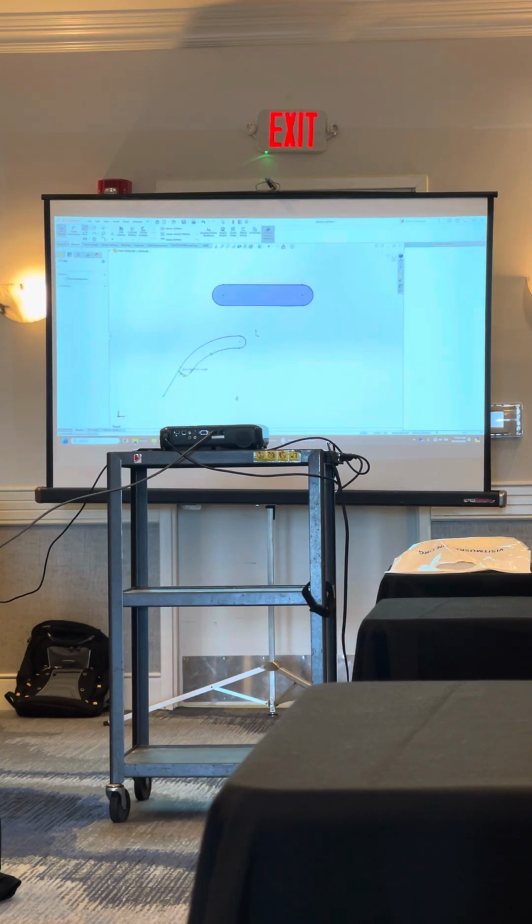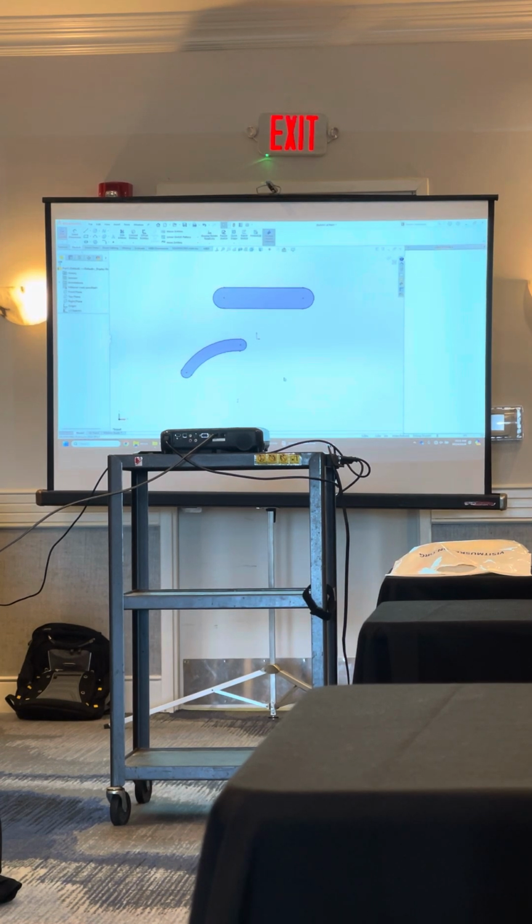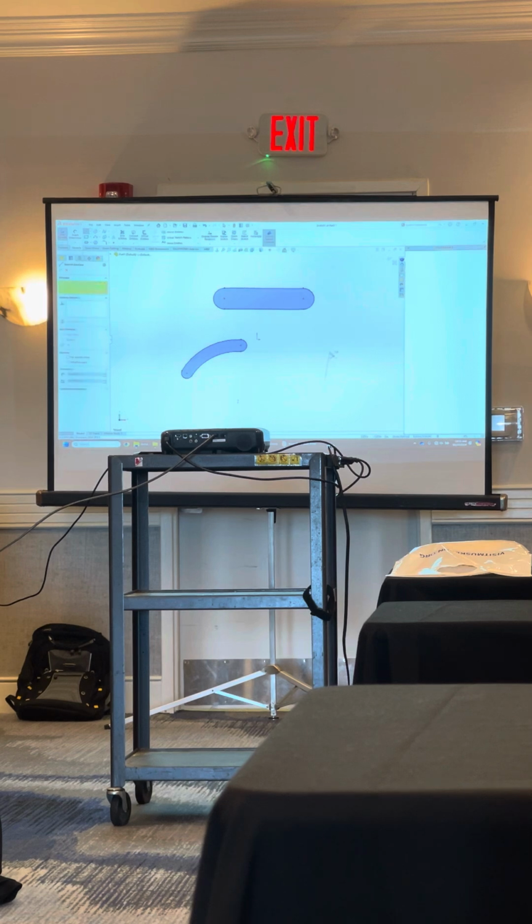So I could just keep on coming around, and worst case scenario, I can delete that line, and now I have a curved slot on there. Needs a little bit of touching up, but again, that is all drawn with the line tool, right? Other conditions it works out really good for is if you have a tombstone shape, and we can easily pull that around.